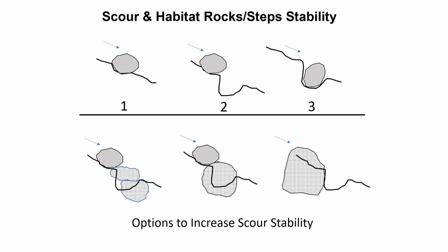Any of these work, and footers are a key element if you're going to put in rocks that aren't locked into other places in order to keep them stable over time. And that is something that we find all the time, is putting these footer rocks are really something that's missed, and contractors don't like to do it. Designers leave it out. Something that you really need if you're going to put these rocks in by themselves.